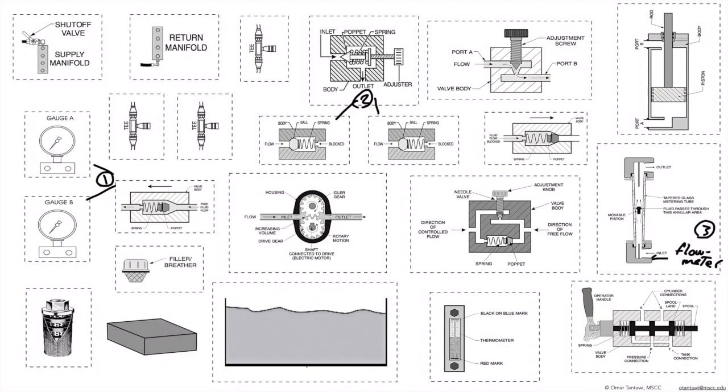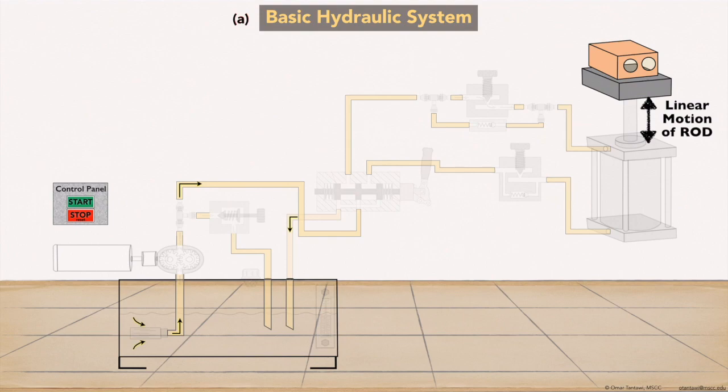The oil comes in on the inlet port. It will go through the annular area and push the piston to a certain level. And once the piston becomes stable at that level, read the marked line, which will be the flow rate. Build the machine on this slide. There are the extra components we just talked about, so I want you to try to figure out where to add them.